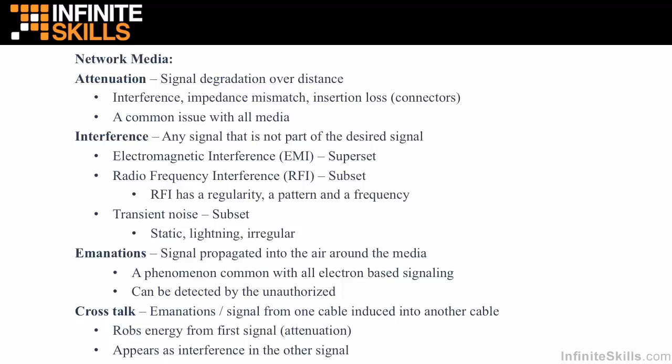However, because we have many wires that might be adjacent to one another, like a cable run, a bundle of Ethernet cables running through the walls or through the ceiling, and they're generally packed tightly together, the emanated signal from one wire induces signal interference into adjacent wires because they cross this airspace where this magnetic field is built. So these emanations cause interference and signal degradation.